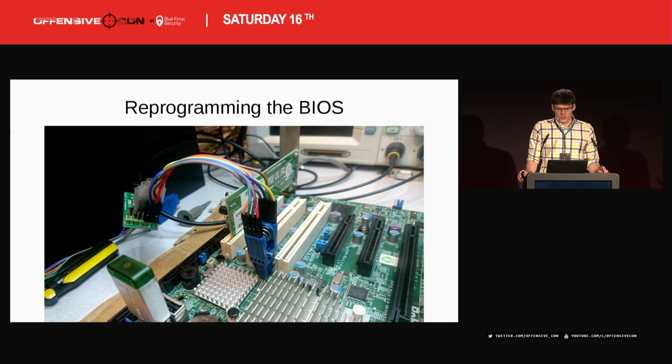Right, so with this hack in mind, we managed to do the cold boot and build the generic victim, the generic memory dumper. This memory dumper now works for any machine that has ECC memory, so you can use any victim with this machine. And I'm going to open source parts of this, so you can use the same board if you want and flash your own BIOS image. I guess you can flash it now even through some nicer interface than the clip that I have there.